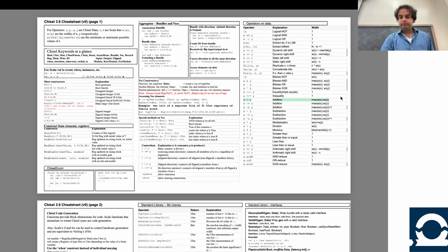It is the maximum width of either input. For now, let's assume I have two n-bit numbers, right? If I have two n-bit numbers and I add them together, because of the number getting bigger, technically the output could be n plus 1 bits, which is why I keep saying it's truncating. By having an n-bit input and adding it to another n-bit number and then getting an n-bit output, potentially there's a truncation possible, right?